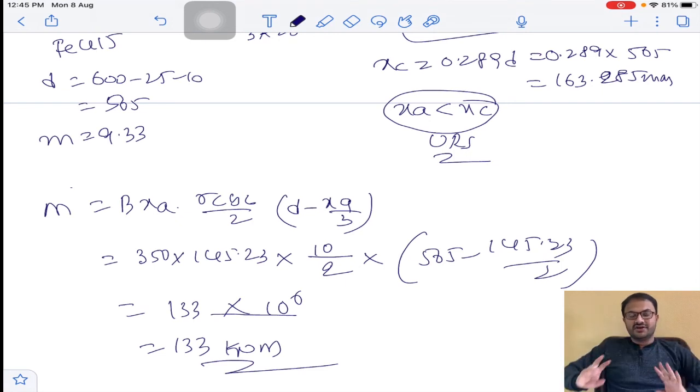Okay, yeah. So now these are all working stress method. Generally nowadays the usage is limit state method. There are only some older constructions like bridges and water tanks where the working stress method is still used, but for modern constructions like beams and buildings, they are not using the working stress method. The course is design of reinforced concrete bridges, so it is related to bridges. The code design is only by working stress method, so that's why you need to solve all this.